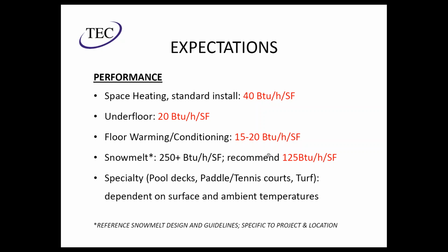This isn't really regarding performance, but these next two are common load profiles for similar systems. In a floor warming situation where the customer is just looking for warm tile flooring in a bathroom or a kitchen, you don't necessarily want to size it for a full output load, and in that situation, you'd be looking at a 15 to 20 BTU per square foot load.